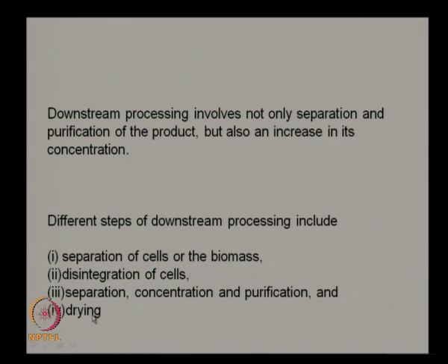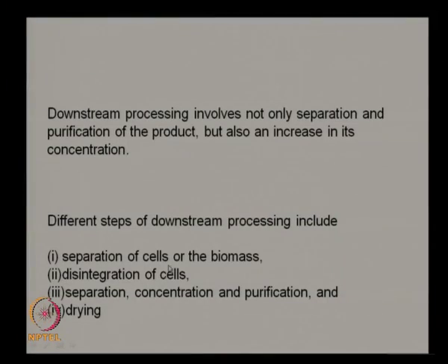And finally if it is a solid material, you would like to dry the product so that all the moisture is removed, because the moisture sometimes leads to instability in the product, especially enzymes lose their activity over a period of time if there is moisture, and that is called shelf life. So if you keep your enzyme with moisture over a period of time, the enzyme may lose activity. So the best thing is to dry it up. So when you dry, even solid material loses its volume, so storage becomes much easier, transportation becomes much easier, so the cost of transportation also goes down. So drying is usually resorted to if you are interested in a solid product.